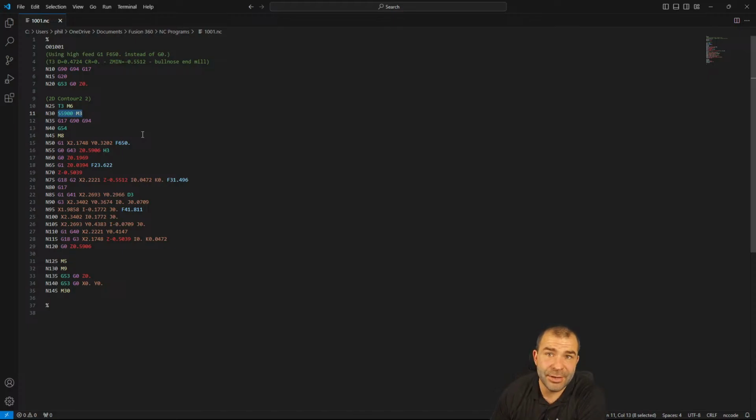Now, some machines have an M code to lock the spindle or an M code to orientate and lock. Keep in mind, you do need to know that orientation call out if it's not perfectly squared up to the machine. You could simply go in and delete this, and then type in, maybe it's a random one, M160 or 144, and then maybe there's a P value 60 or 50, which is the angle of tilt. So you could actually turn the head and orientate your spindle based on a certain degree as well. But then you would run your cycle normal as can be.